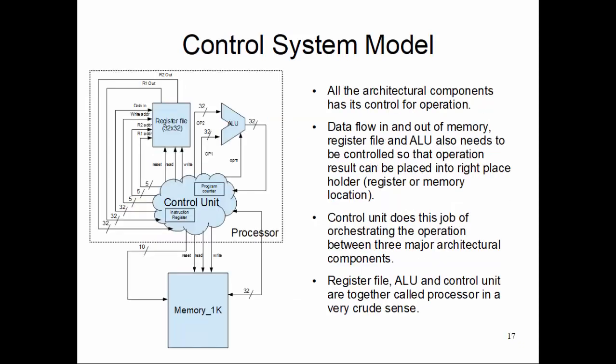Your program counter is a very special register for each type of processor. It resets to a specific value, which is not zero, by the way. If someone resets this special register, it resets to a specific value which is defined in the processor's manual.